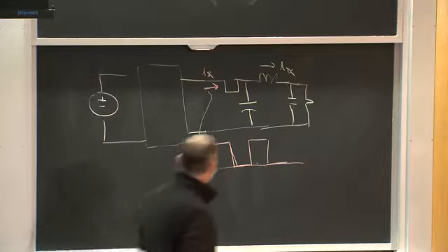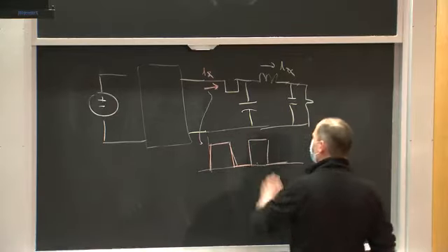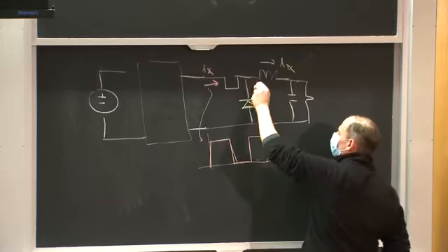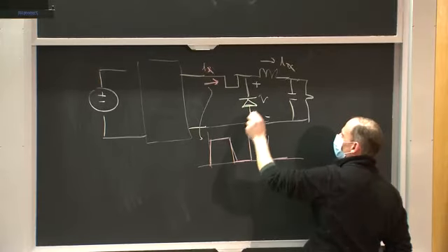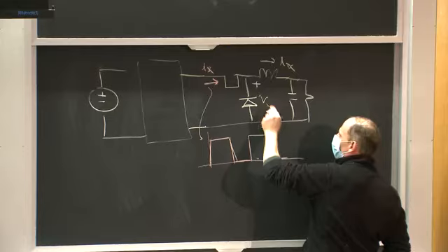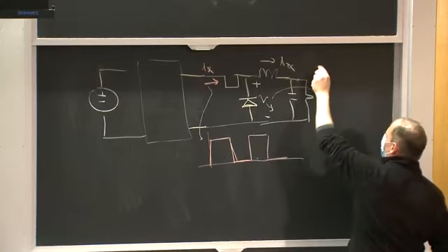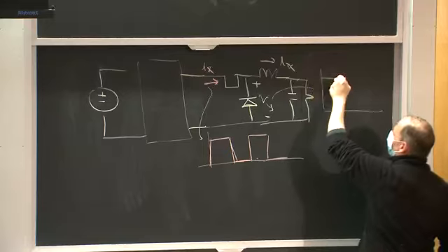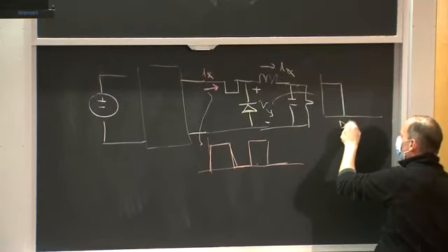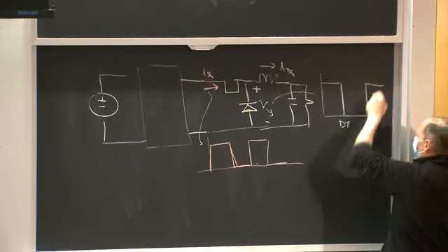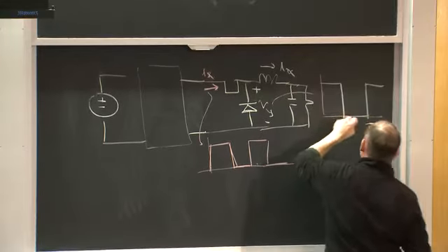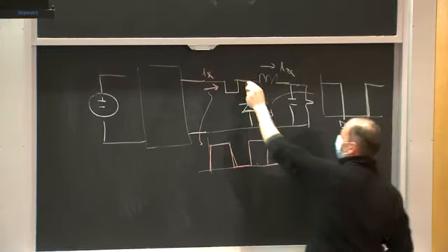Likewise, if I looked at, it would be helpful if I put a diode here instead of a capacitor. If I looked at the switch voltage, let me call this Vy, right? Vy has the same sort of shape, right? I have high for some time dT, and then low for the rest of the cycle, right, for T. And I've got this very sharp-edged waveform right here, okay?